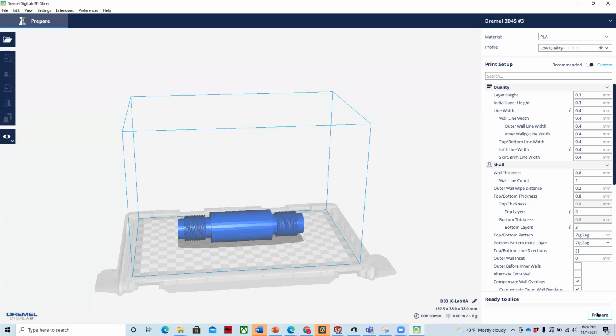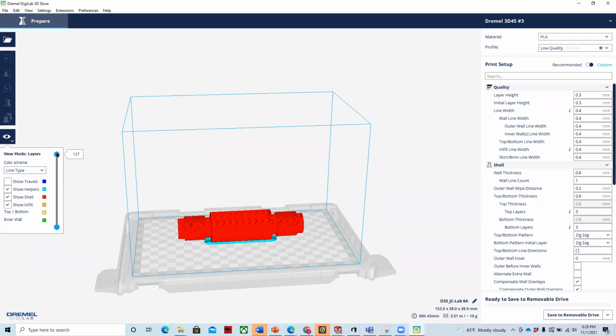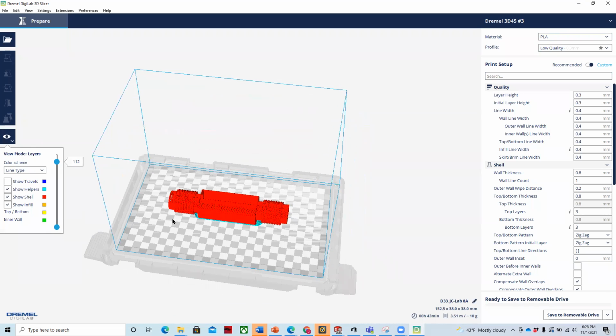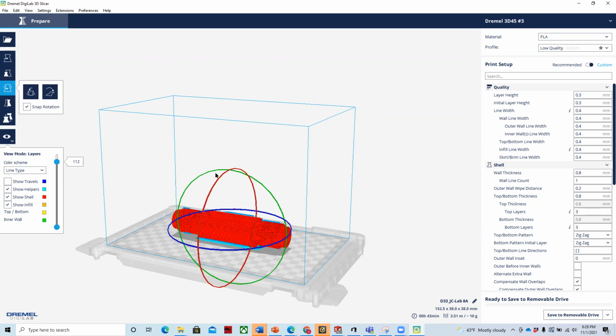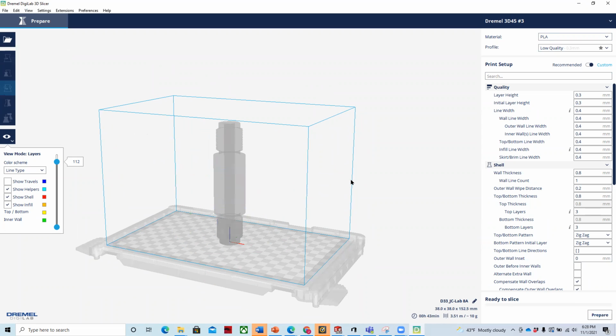And then what we do is we prepare it in the slicer using polylactic acid or PLA. Prepare it. And then I can look at the layers and see how that would come out. Typically, when I 3D print something that's round like this, what I recommend people do is you stand it up on the edge, because when they're up on the edge, the round cylinders stay more cylindrical in shape like that.